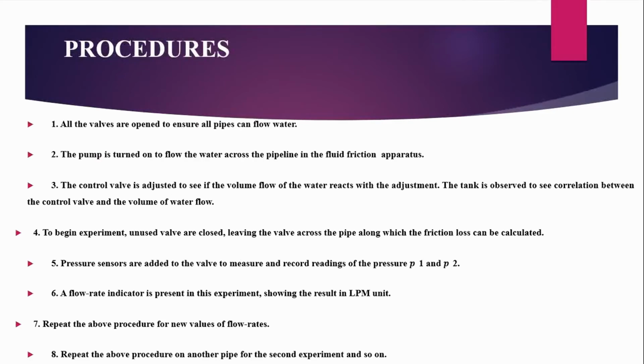Moving on to the procedures, there are totally 8 procedures for this experiment. First is opening all the valves to ensure the flow of water. The pump is turned on to flow the water across the pipeline.